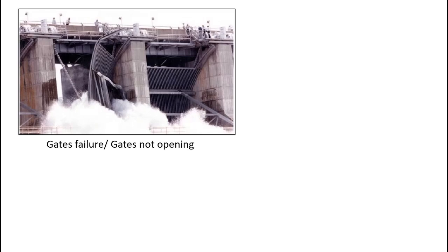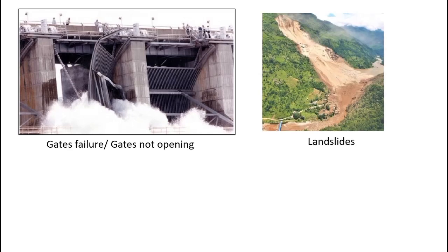For any dam to operate for more years, its gates should function properly. There are standard operating procedures for gates maintenance and other hydromechanical components. Even if we provide enough number of gates to pass the inflow flood, there are chances that these could not be operated due to their operational issues. If gates are not opened, overtopping causes dam failure. If gates are washed away or broken, uncontrolled release of water happens which may sometimes damage other parts of the dam.